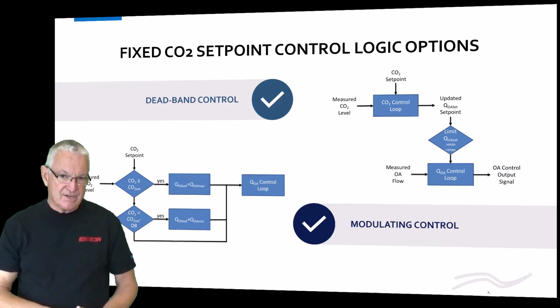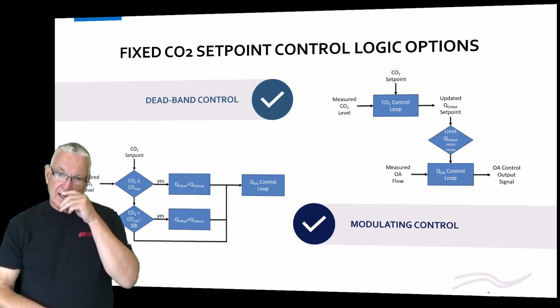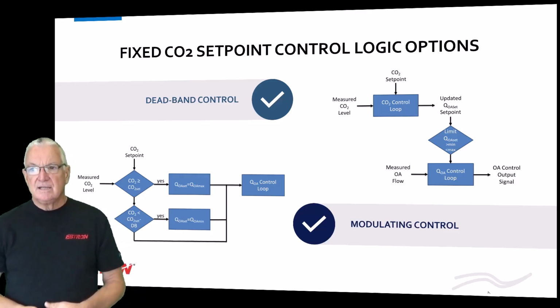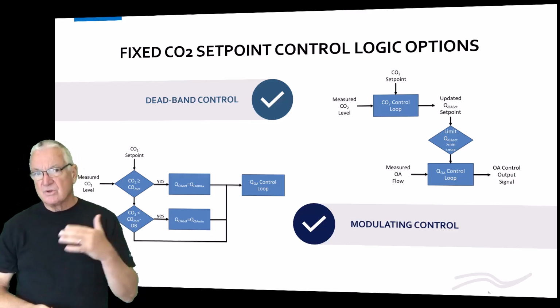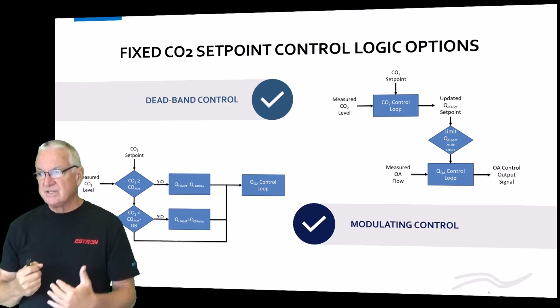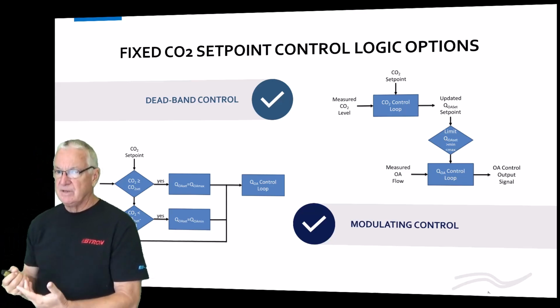You can look at that logic. It's pretty straightforward. That's the one on the left. On the right, modulating control. The one on the left is going to have two control points. The one on the right is just going to modulate between the min-min and the min-max.